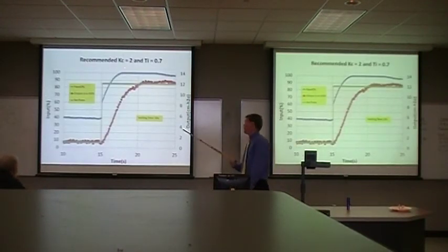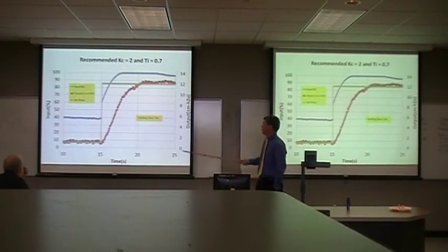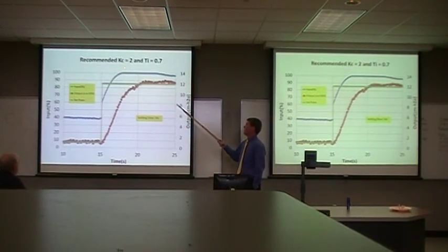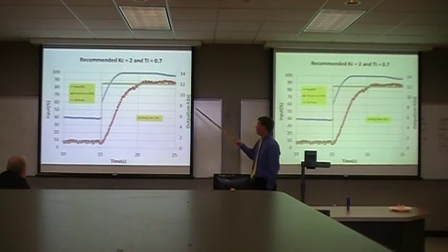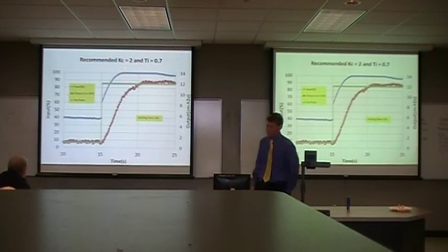This is a graph of the one that I said was recommended for the entire system. I tried to do the biggest jump that you could possibly do for this system to see how it would react. Unfortunately, it did have some wind up, but it still settled within 10 seconds to what the customer desired. So essentially, the maximum settling time was 10 seconds.